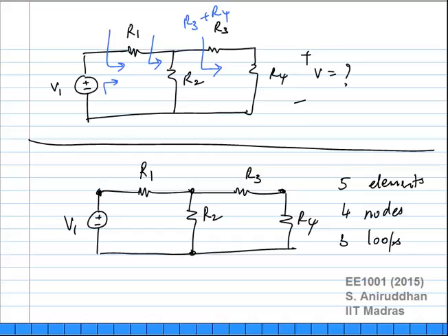If I gave you a very complex circuit with some n nodes, right? Of course you can write KCL at each one of these nodes. It will always be valid. But for a general network with n nodes, how many independent KCL equations can you have and why? What? Somebody said some number? N minus 1. Why is that?